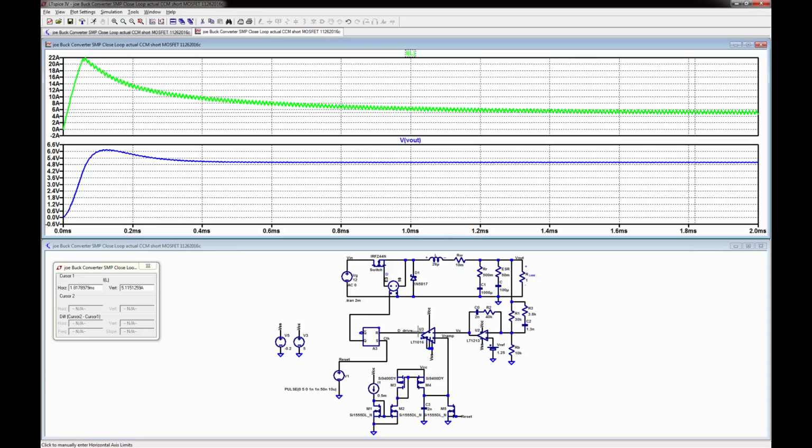See, right now, we're putting out a large duty cycle, the max duty cycle, because at the beginning the output voltage is low, which means this is pinned low and this will be pinned high, which gives us maximum duty cycle. We don't want that to be the maximum duty cycle here. We want this to be slow. That's why we're going to have to add a soft start, okay, to get rid of this initial current.